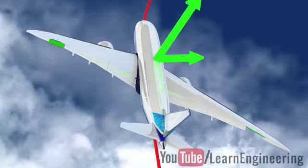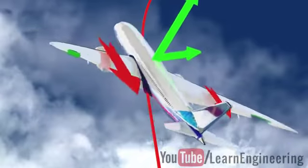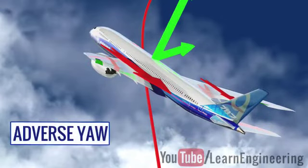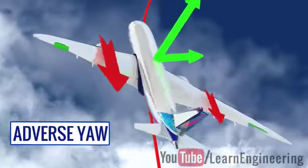When you keep one aileron up and the other aileron down, the drag forces induced on the wings are not the same. This will cause the airplane to yaw. This phenomenon is known as adverse yaw. The rudder has to be operated simultaneously to prevent the adverse yaw.